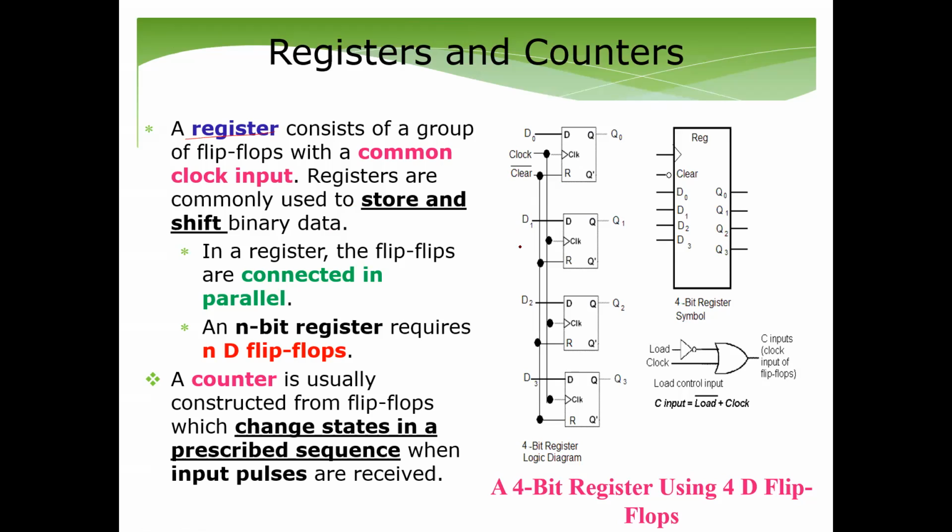Quick revision on a register. What's a register? A register is just a group of flip-flops. All will have a common clock input, but different data input. And it should also have a common reset signal. So you have common reset, common preset.